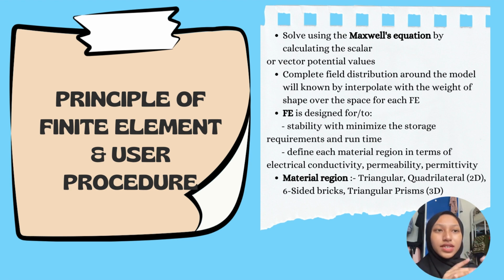So each region is then divided into triangular and quadrilateral elements for 2D, and six-sided bricks and triangular prisms for 3D, with size depending on the field changes.